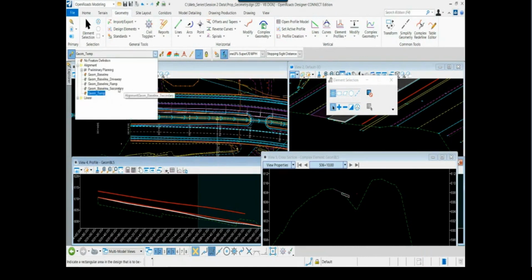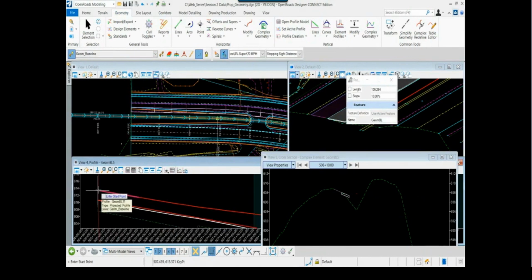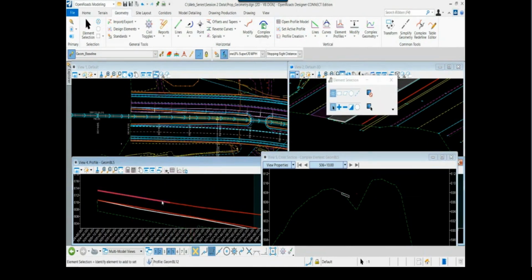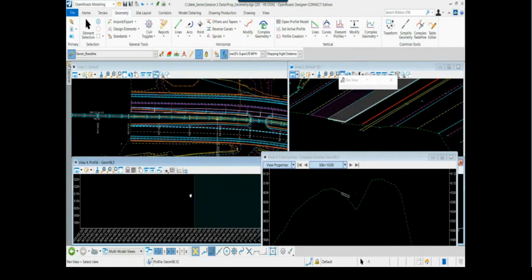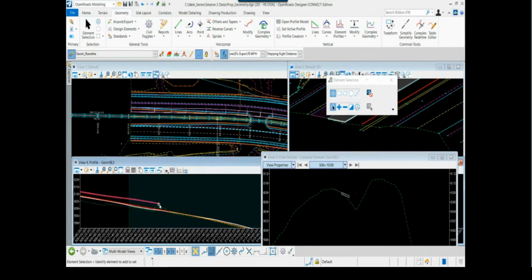We're going to create the vertical tangent first. Again, I'm going to snap here so that I'm following this. I want a smooth transition. Okay. Let's snap our vertex to there. So I now have an additional geometric element based off of that graphical display of the edge of pavement. And now I want to control the transition into that, again, common PGL area, non-bifurcated area. To do that, I'm going to go back. I'm going to use profile line again.